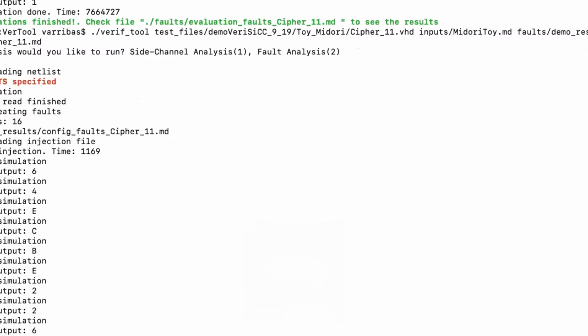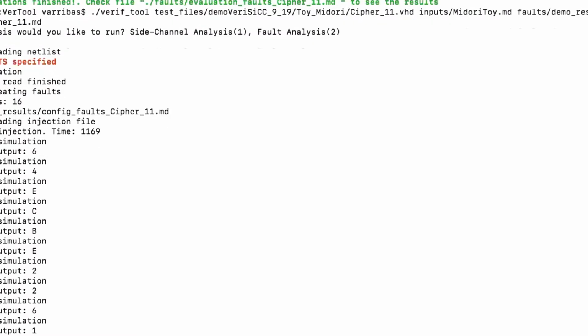So we have here a round-based implementation of Keccak. This is not the full implementation, but only the data path, which covers all the permutations. This is a two-share implementation using DOM protection. We have our two-share inputs, and here we only take the combinational part. We output the expanded 4 shares from the nonlinear layer.